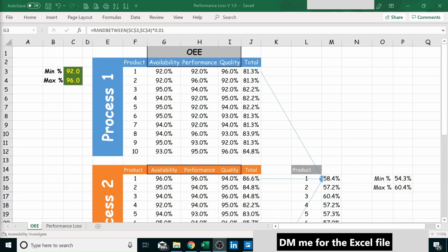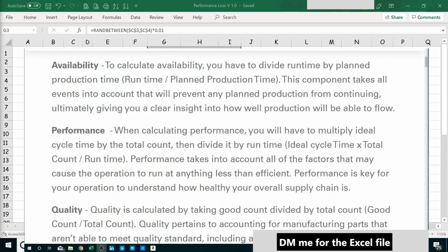So real quickly here, overall equipment effectiveness basically is a multiplication of three different measurements. The first one is availability, or a lot of people call it uptime. Is that machine running all the time that it's supposed to run, or did it go down for some reason? Some unplanned maintenance, for example, needed oil, it was overheating, or a gear broke or something. So, in order to minimize unplanned maintenance, breakdowns of the machine, we need to get better at planned maintenance, which is preventive and even predictive maintenance.